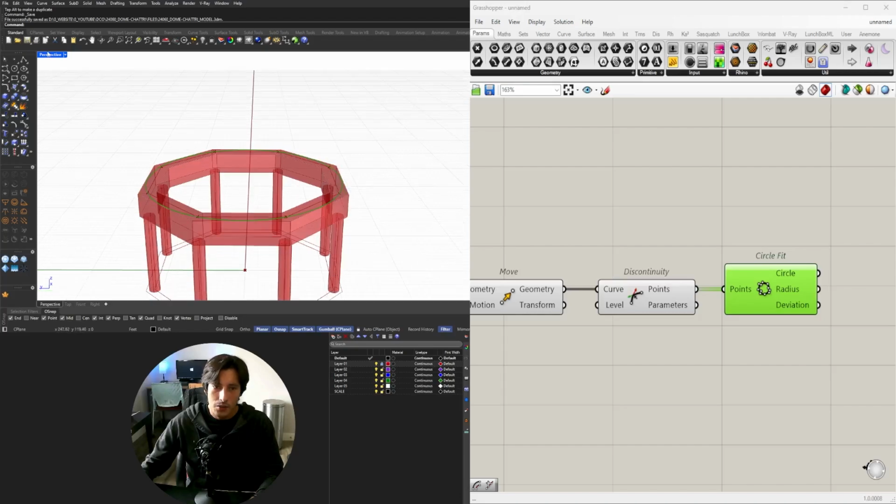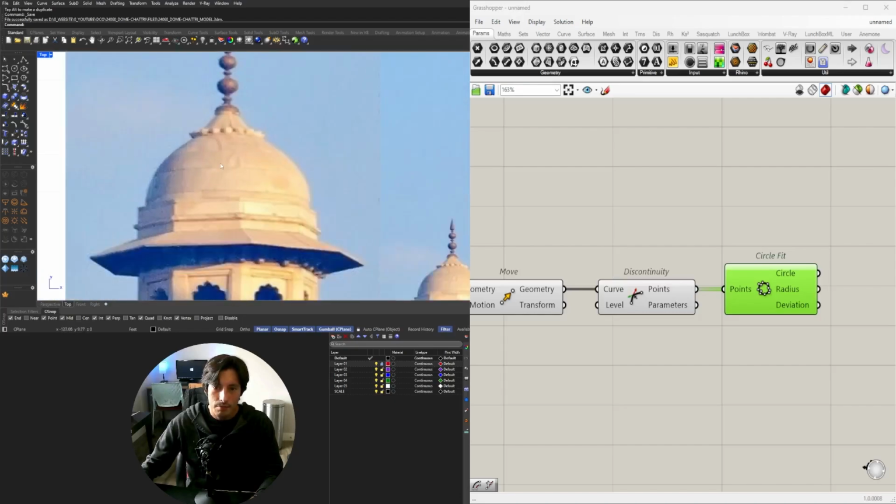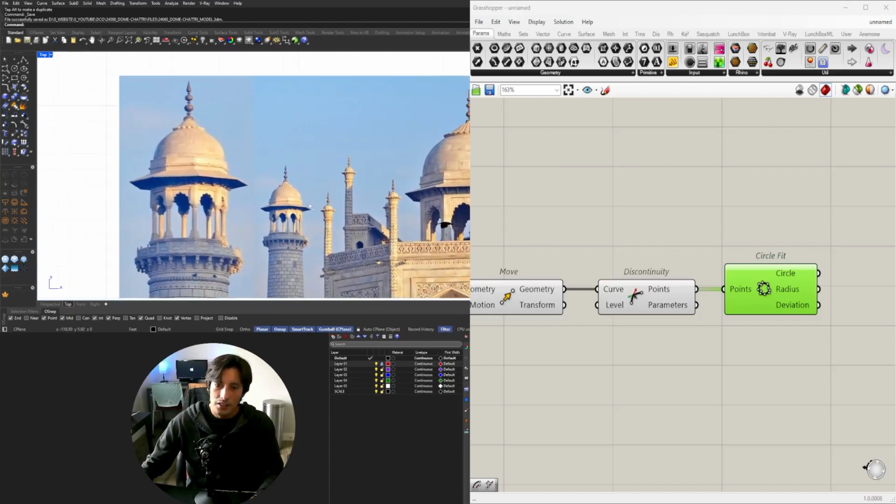Now here's the question that I have when I'm looking at this. I am not sure what happens here, so this is more of our call. Is this a full dome that has this thing on top, or is it a dome that is pointed? I don't know. The reason I say that is because depending on what approach you take, you would come up with a different result. So on this one, I'm actually going to be creating 3 points, creating a line segment, and revolving it around the center.